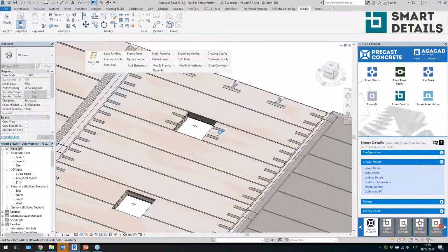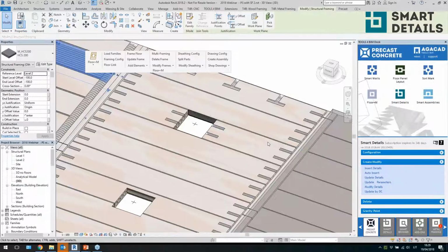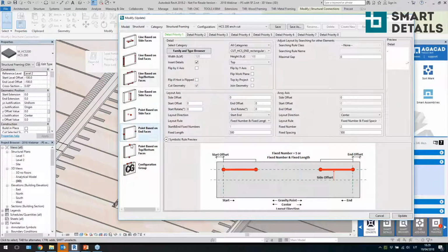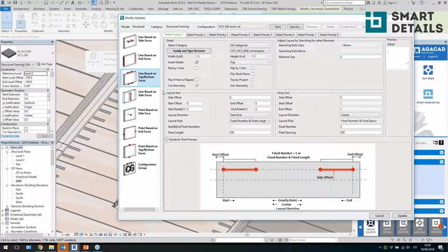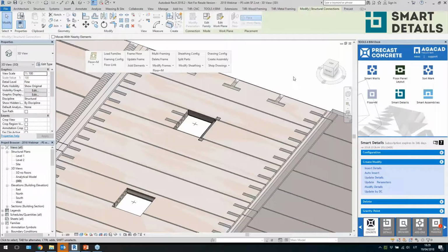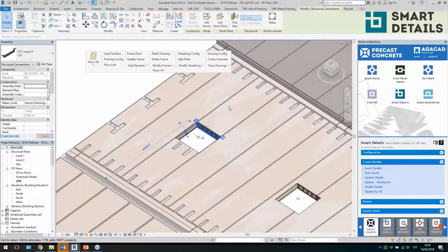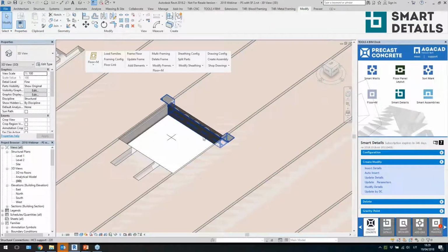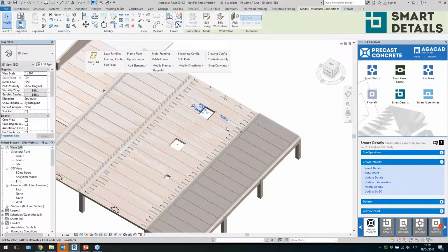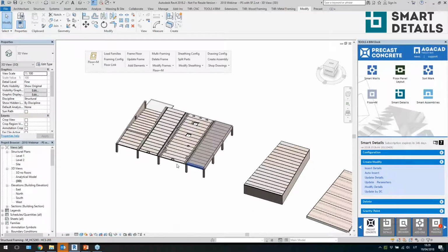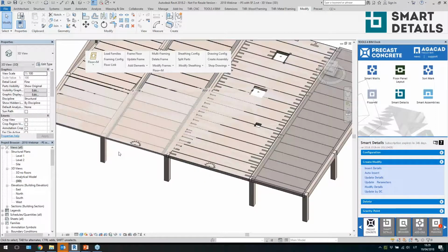Let me do that again. Click on this detail, click on modify. Okay, over here, I want to insert this one just at the start of my slab, and I don't want to have these at both ends. I want to have this just at the end, and just click on update. So you see now I modified just this particular slab, right, with some additional detail inserted. Of course, I can do the same for this one. But I hope you got the idea about what's possible here.